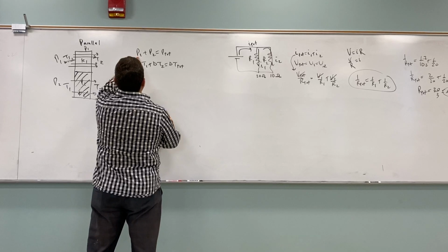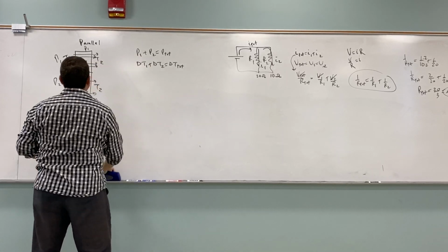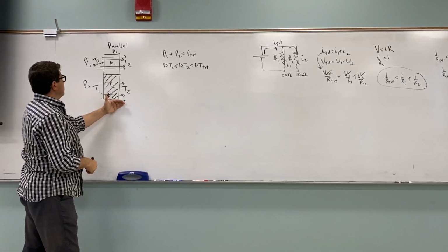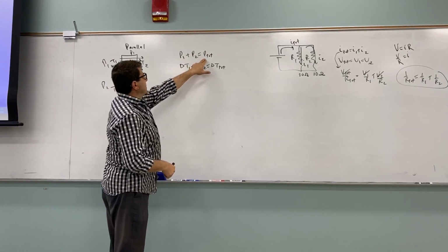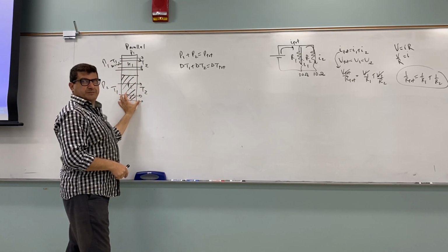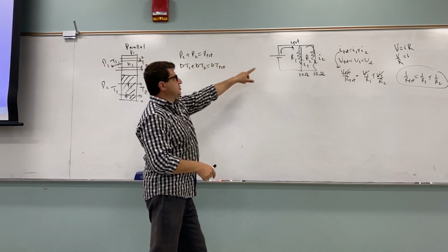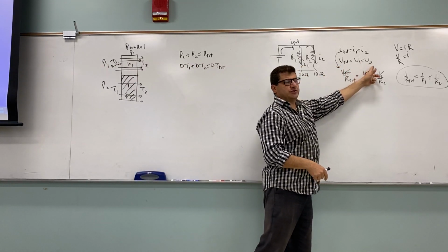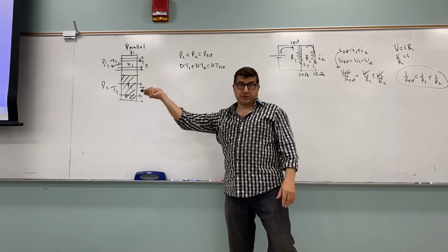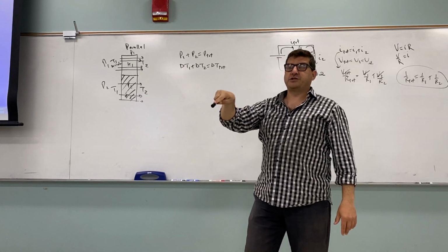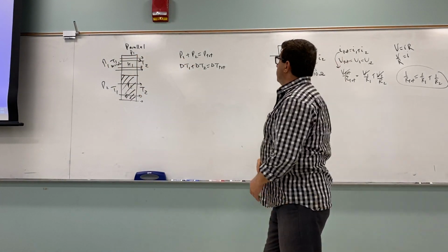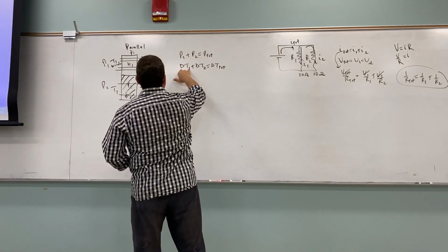say, okay, what adds up? What is the same? Okay, we never said that. So what is the same in this case? Right? We said the power adds up, but what is the same? It should be similar concept as to here. What is the same? Voltage, right? And the equivalent of voltage for heat is temperature difference, because there's temperature difference that drives heat flow, right?